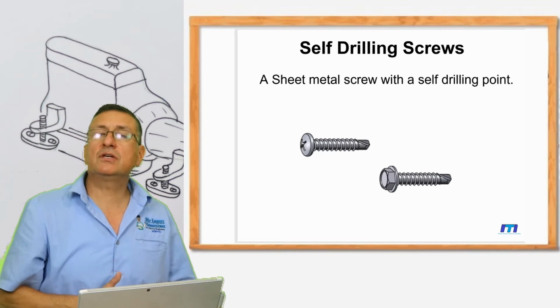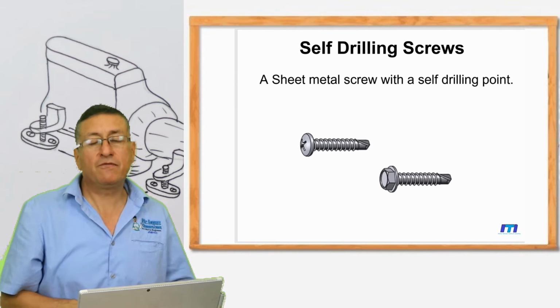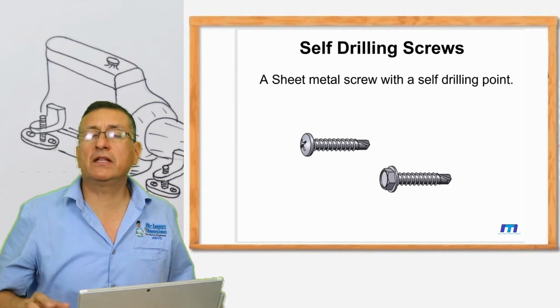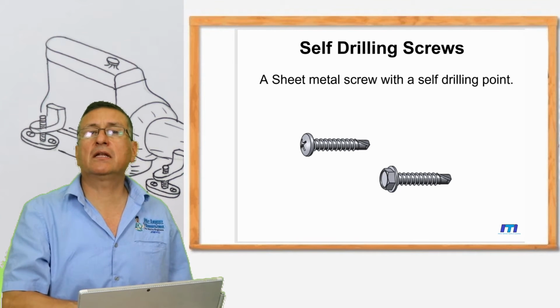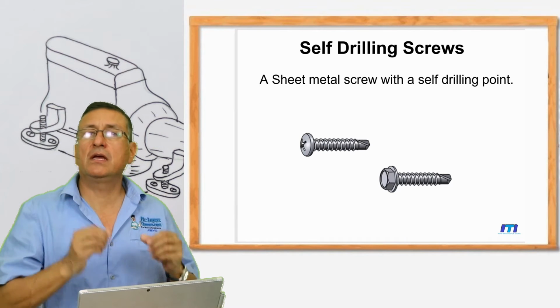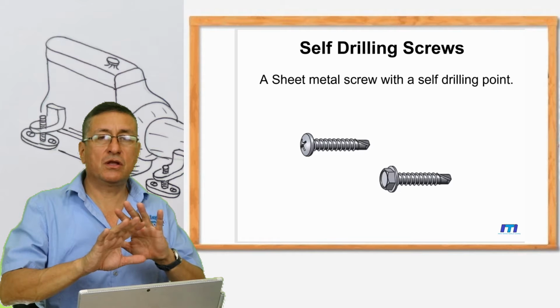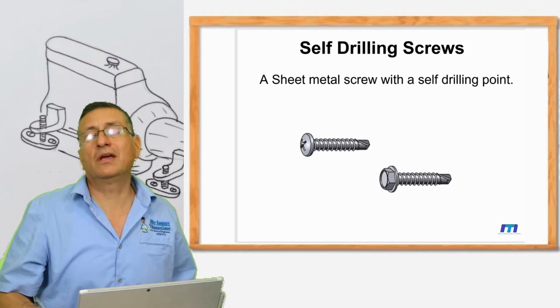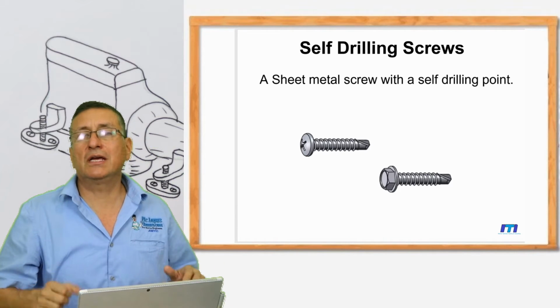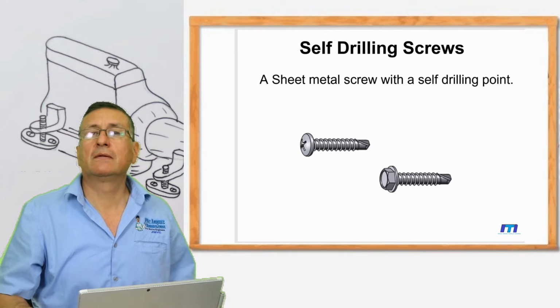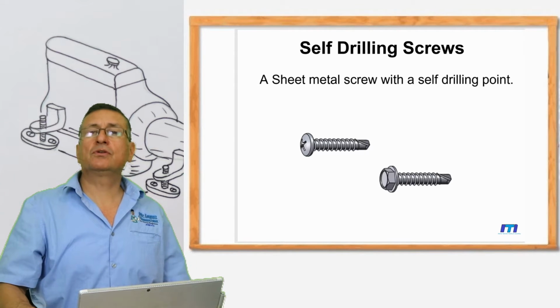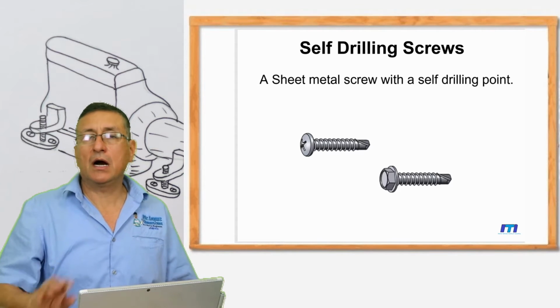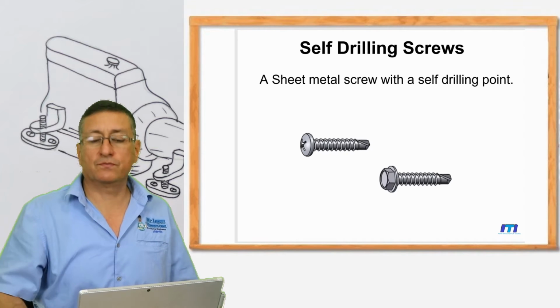If it's 300 series, it is marine approved. If not, no. How can you verify that? With the magnet. You approximate the magnet and you verify if it's fully zero corrosion, or if it's medium, or is pure steel. Those screws, those bolts should be 100% zero corrosion.